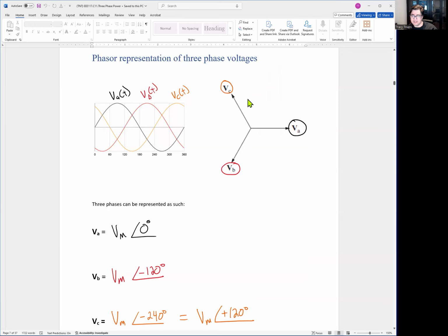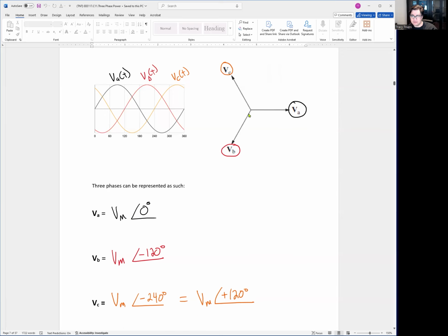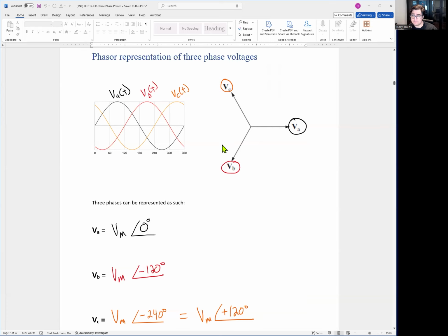But the big thing is this equal 3Y. It's like the Mercedes-Benz emblem. It's 3Y, it's 3 vectors equally distant 120 degrees apart with the same magnitude. Okay. That's how you represent a balanced three-phase source. This is physically what's going on with the actual waveform, but a lot of people like to draw vectors because it's easier to read than a graph with cosine and sine functions.